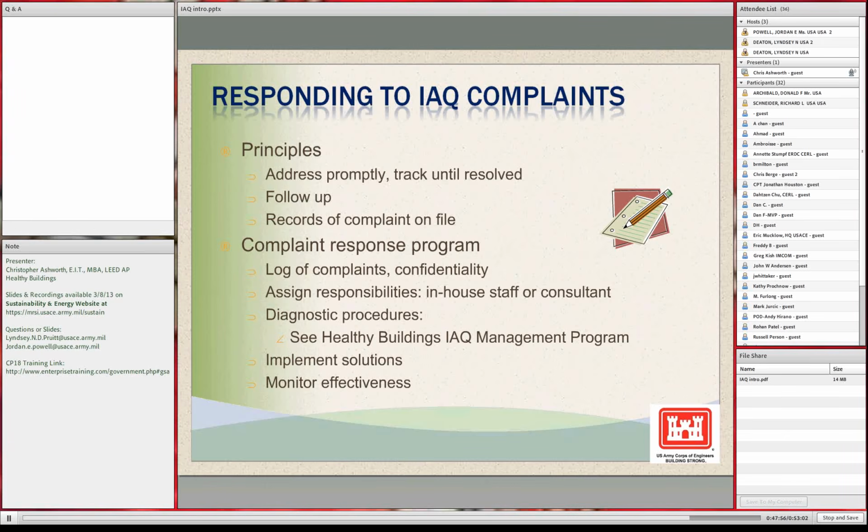locations. I used to work for Pfizer in a clean room, and that's the prime example of proper pressurization. Or a surgical suite is another one. You don't want your surgical suite to be under a negative pressure for obvious reasons, the various contaminants and the various pathogens and bloodborne pathogens that can be moved through the air. So that's managing the pressure of the building and those individual spaces is huge. If you can get your whole building under a positive pressure, so you're not perpetually sucking in, you can go a long way to resolving pressure issues.